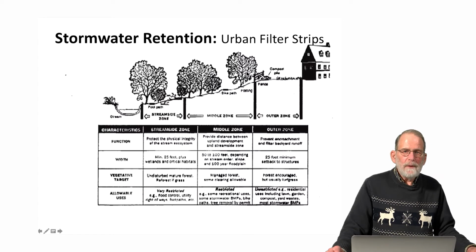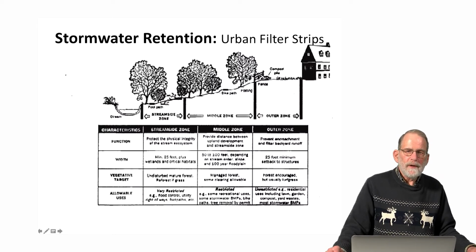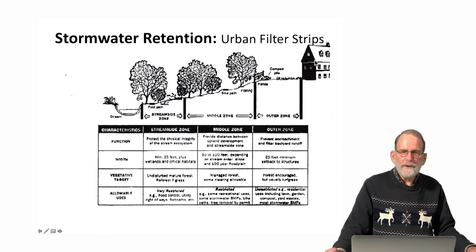We can apply the same concept in an urban context, where we can begin to talk about runoff coming off of a hard-surfaced, developed landscape, slowing that runoff down by the way we treat the slopes coming into a low-lying area, trying to promote as much infiltration of water, storing the water as it moves along, infiltrating that water so that the amount of water that's discharged into the adjacent surface water system is greatly reduced.